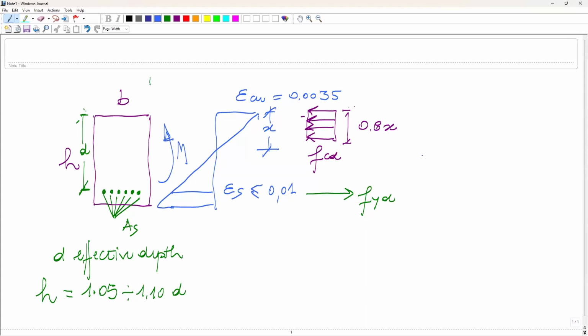Well, because one of the assumptions that we make in reinforced concrete design is that there is perfect bond between steel and concrete. So the concrete around that bar, even if it's in tension and we neglect it in the design, you see there is no tensile stress in the concrete part. But the concrete is there and has to follow the steel. Otherwise, you do not guarantee the connection, even if this concrete part does not participate in the strength. Otherwise, you have bars which go by themselves and concrete which goes by itself.